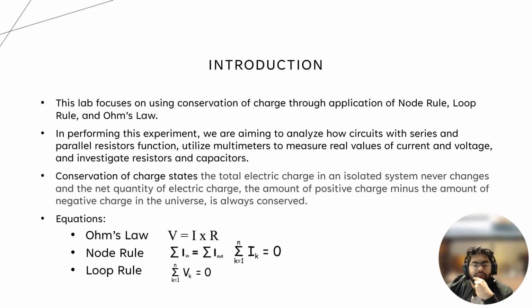So to introduce the lab, we're focusing on using the conservation of charge through application of the node rule, loop rule, and Ohm's law. In doing the experiment, we're trying to analyze how circuits with series and parallel resistors function, utilize multimeters to measure real values of current and voltage, and investigate resistors and capacitors.